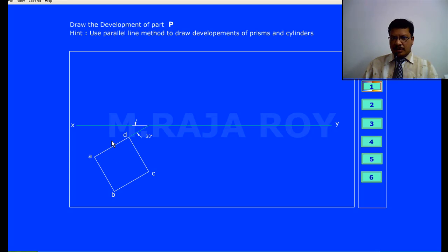From the top view, project the front view. The next step, I am projecting the front view. Now I am drawing the projectors. Here side of the base is some 50 mm. So with 50 mm height, I am projecting the front view. This is A dash, this is B dash, because this B face edge is visible while I am seeing like this. So this is visible B dash. Next visible is this one, C dash. Now this D face edge is invisible. So in the front view, D dash is invisible. So if you mark the center point here, and if you project, the axis will be somewhere here. So projections of solids part is completed.